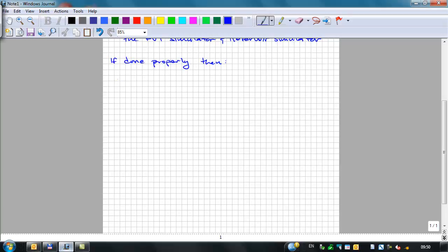First, you should get the same initial gas-oil ratio. We're going to talk mainly about oil-gas ratios, which is just the inverse of that, in the two models. With the same initial oil-gas ratio, you basically get the same oil in place, the same gas in place, for the two simulators. More important than that is that you should get the same, and when I say same, it should be almost line thickness. Line thickness is almost the same.